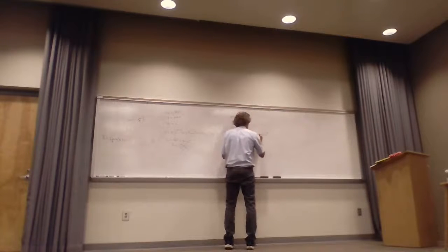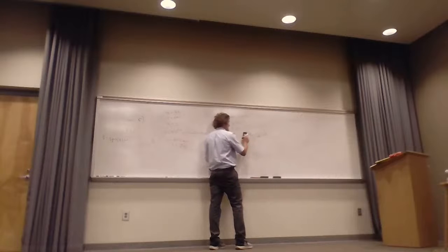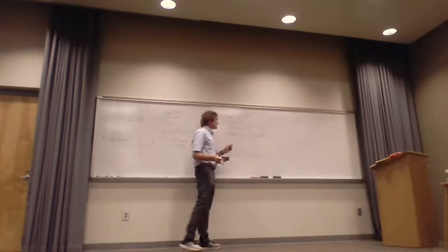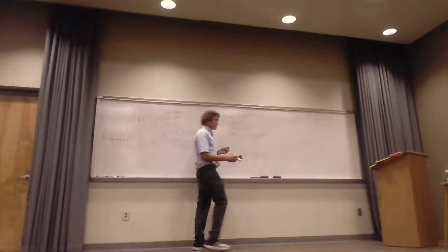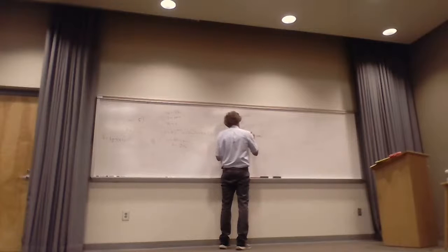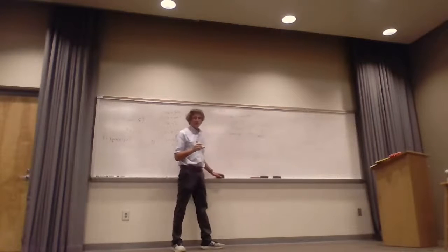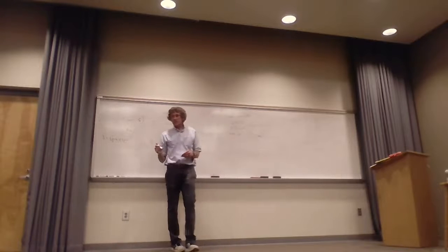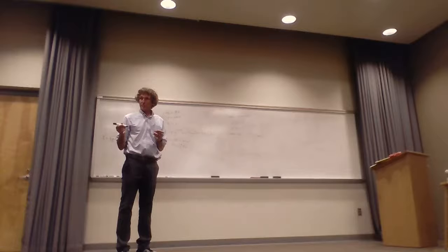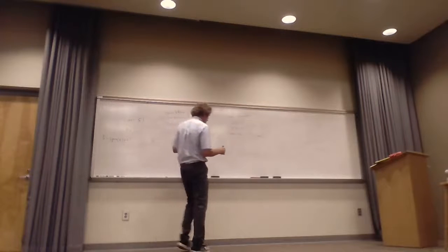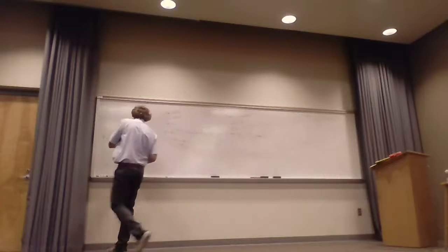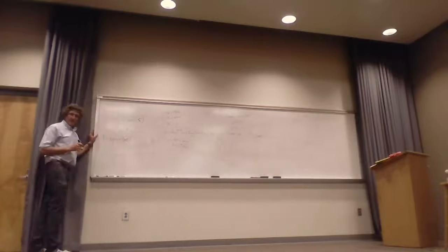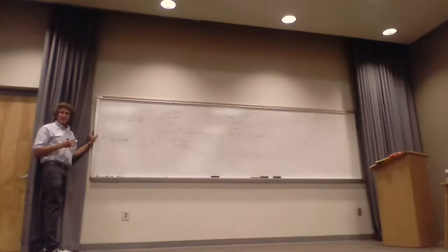Now, when you look at this, I've got 10 to the 9th and 10 to the minus 9th. That goes away, right? So I have 72 over 18, which is what? 9 over 36 is 4, right? So this whole thing is 4. And that means, in fact, the conductivity is much greater than omega epsilon, right? Now we can make the assumption it is a good conductor. Do you all agree with that? All right, if it's a good conductor, and if I didn't prove this, you tell me, you can assume that term goes away, can't you? Because j omega epsilon is much, much less than sigma. Do you all agree with that?